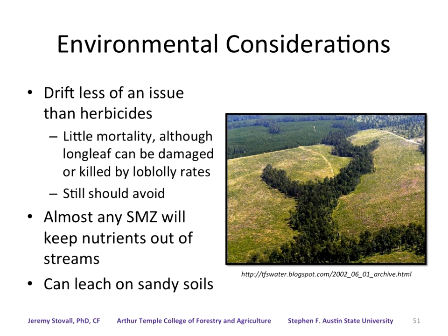Obviously you don't want to apply fertilizer right to the SMZ, but consider forestry compared to agriculture, where with forestry we're generally using lower fertilizer rates, and even the most intensive land managers may be applying fertilizer, say, 4 times in a rotation versus on an annual basis in agriculture. So we have a lot of issues with the dead zone in the Gulf of Mexico and eutrophication in streams from too many nutrients in the stream. Forestry really isn't the source of that. We find that we do very, very well with our fertilizer application, and it's not really moving off-site.